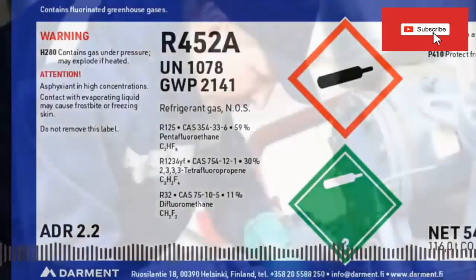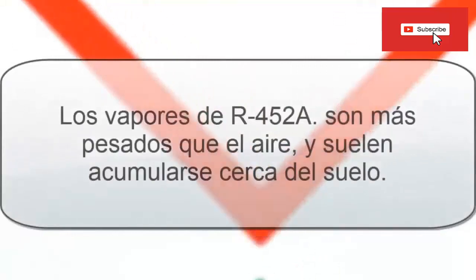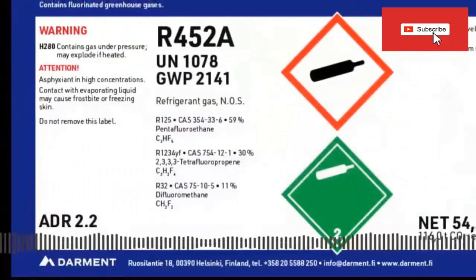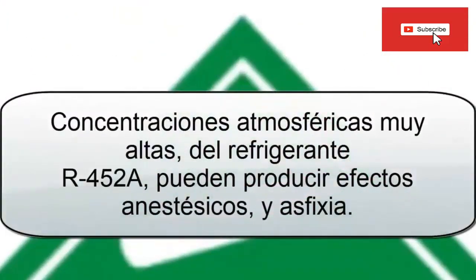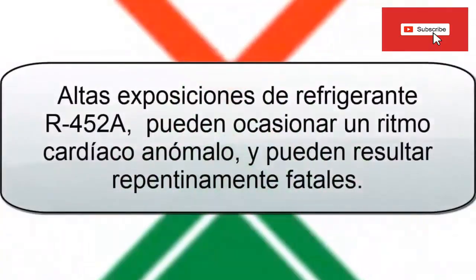14. The R452A refrigerant is also used in new industrial refrigeration installations. 15. R452A vapors are heavier than air, and tend to accumulate near the ground. 16. Very high atmospheric concentrations of R452A refrigerant can produce anesthetic effects and asphyxiation. 17. High exposures to R452A refrigerant can cause an abnormal heart rhythm, and can be suddenly fatal.